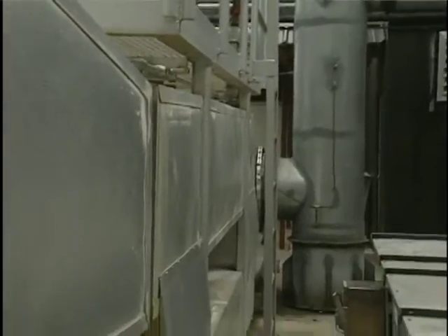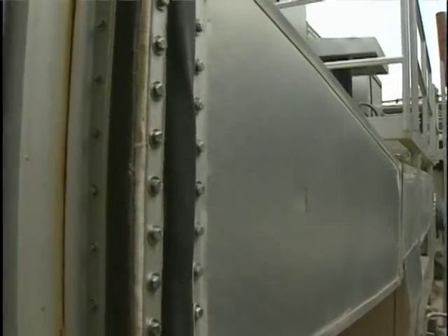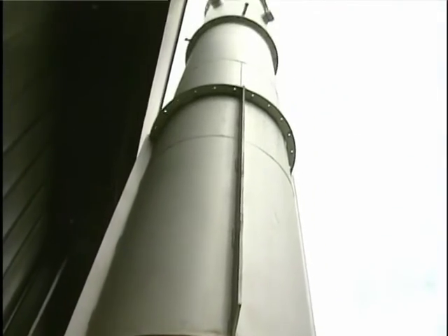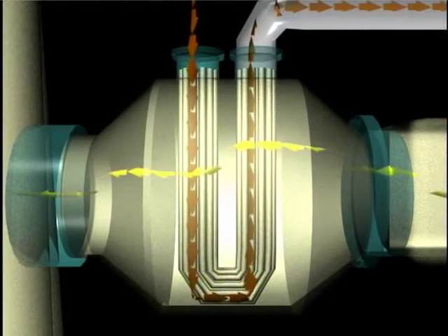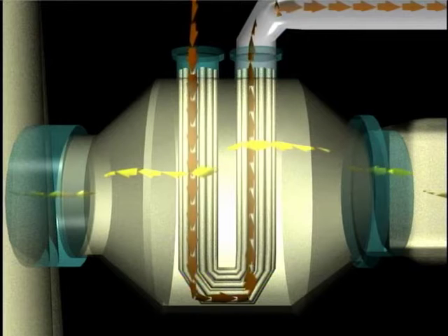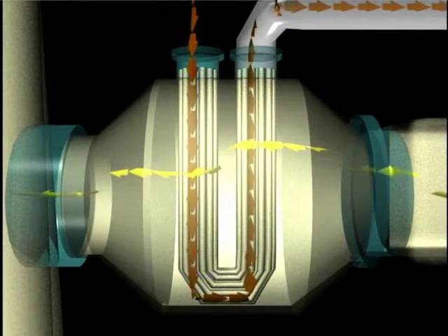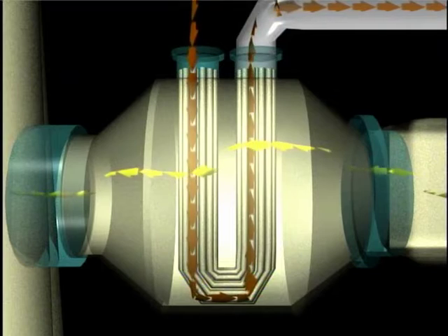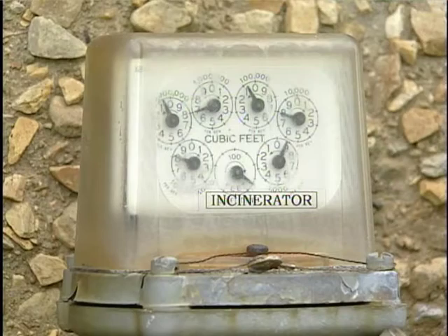If the outlet temperature is being monitored, then records should be examined to detect high temperature excursions, since these could damage the catalyst or downstream heat exchange equipment. The increase in the temperature of the waste gas stream across the heat exchanger provides a useful indication of its physical condition. The accumulation of particulate matter in the heat exchanger reduces transfer efficiency, resulting in increased fuel requirements.